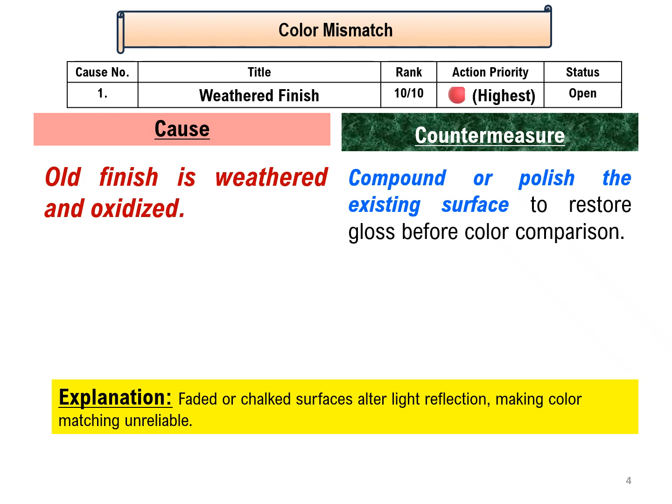Coming to causes and countermeasures, number one, weathered finish. When the finish is old, it is weathered and oxidized. Faded or chalked surfaces alter light reflection, making color matching unreliable. Therefore, compound or polish the existing surface to restore the gloss before comparison.